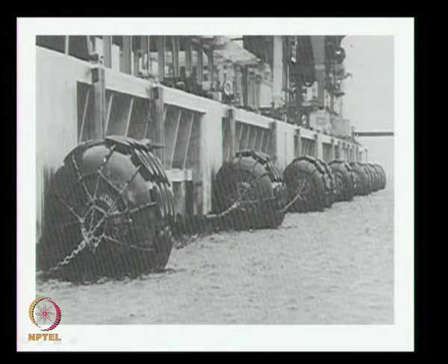You see the rubber bag, the weight is very heavy, so the buoyancy will take care of the weight. Then we have the chains which are connecting it to the structure, but we need a concrete face where the fender is connected. You cannot have an open face like this, so we need a concrete face.